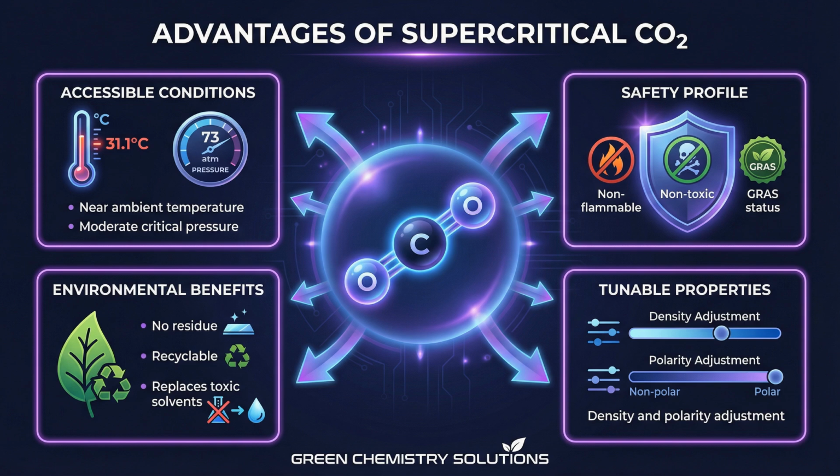Carbon dioxide has become the gold standard of supercritical fluids for several compelling reasons. Its critical point is just above room temperature, meaning you don't need to heat materials significantly, protecting heat-sensitive compounds. The critical pressure, while substantial, is achievable with standard industrial equipment.